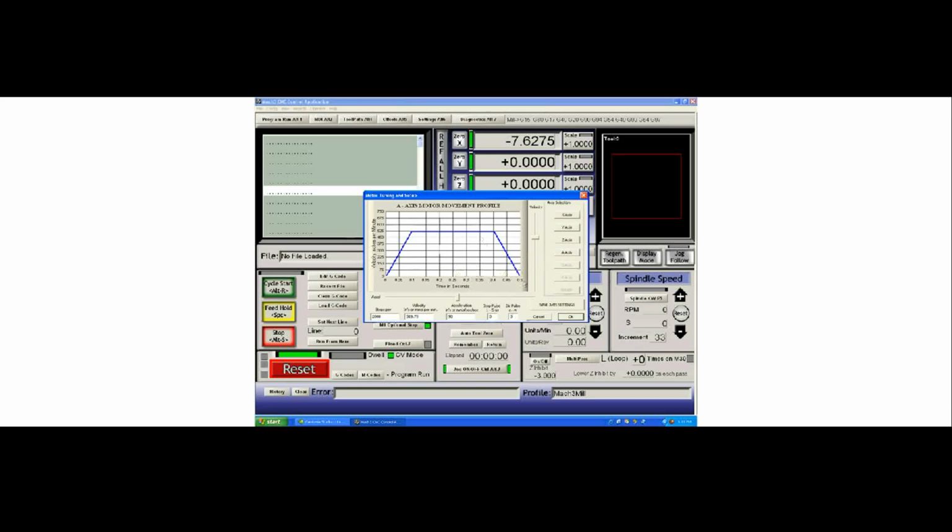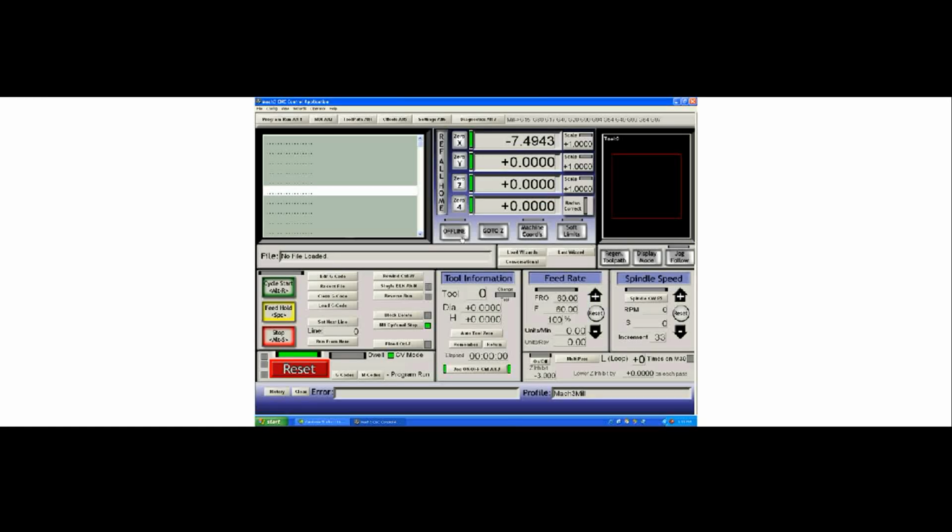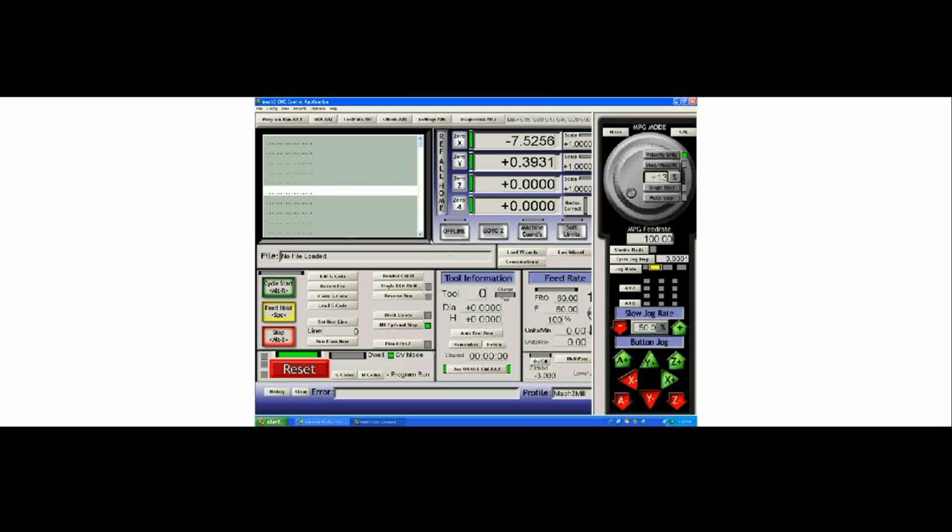So at this point, you should have basic movement. If you hit OK and exit out of that dialog, using the arrow keys on your computer now, you should see your axes jogging around. There are things that could stop that from happening, however. Pressing the Tab key on your keyboard will bring out the Jog Control tab. You'll see here a number